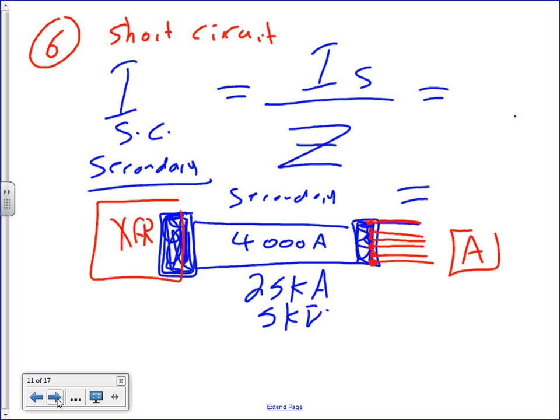The last thing I added here, guys, is the short circuit rating. This is really good to know. Short circuit rating for the transformers is on the secondary side. So to find the short circuit rating, you need the secondary current and the impedance. Piece of cake. The secondary current, my friends, we just found it: 1390. Divide this by Z. Z is the impedance.